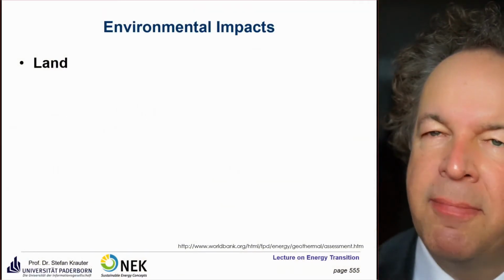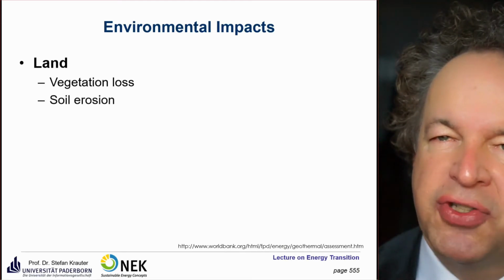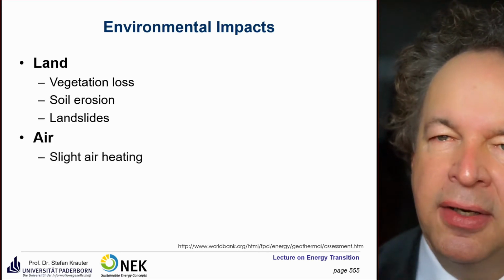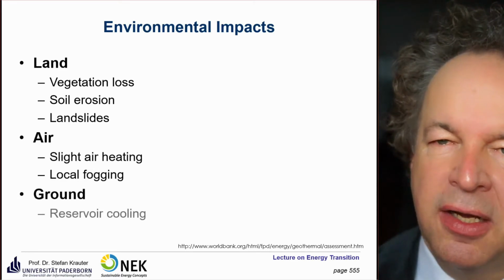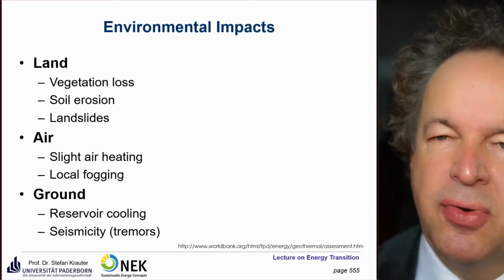Also, you have to consider environmental impacts. You have some vegetation loss, soil erosion, sometimes landslides. For the air, you have slight air heating and local fogging on the ground. You have reservoir cooling, and sometimes tremors.